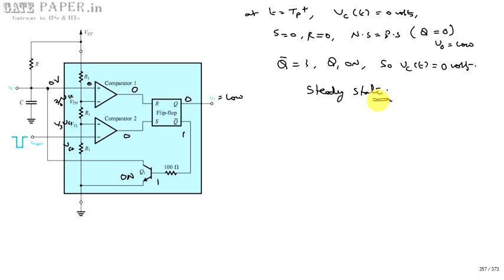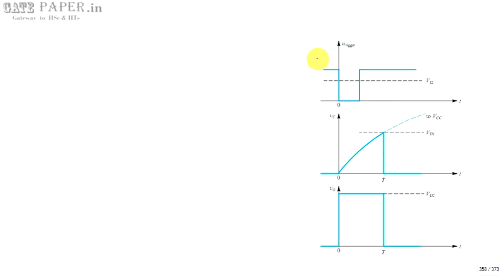If you observe, this is going to be the graph. Whenever t is equal to 0, you apply a trigger pulse. As you apply the trigger pulse, this is 0 minus and this point is at 0 plus. From 0 plus onwards, the capacitor charges exponentially with time constant of R and C. The capacitor could charge towards VCC, but because of the conditions prevailing in the circuit, as it is connected across the input terminal of the op amp, it goes only up to VTH. VTH value is 2 by 3 VCC.